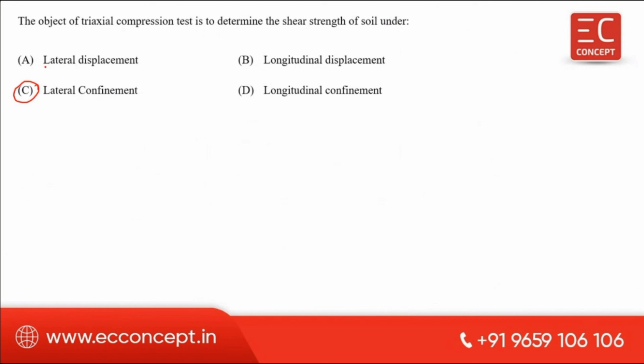Why is this the answer? Consider the test procedure of the triaxial test. The test specimen is prepared like a cylinder. The first thing is we give a confining pressure over the soil sample, this is sigma 3.